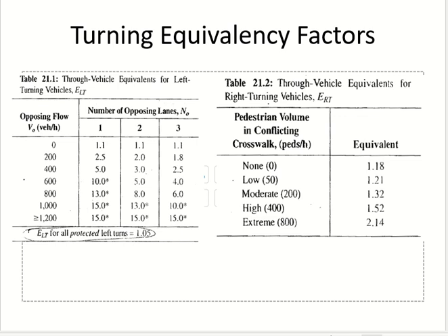But what if I have 100 passenger cars here, 100 passenger cars here, 100 passenger cars here, but this one is for turning. Maybe this one had 2% trucks, this one had 3% trucks, this one has 10% trucks. So I could not compare between them. I converted all of them to passenger cars, so now I can compare. But now the new problem came that this one is turning. So although this is 100, this is 100, this is 100, this 100 is turning. So how can I compare? Now I need another equivalency factor for turning.